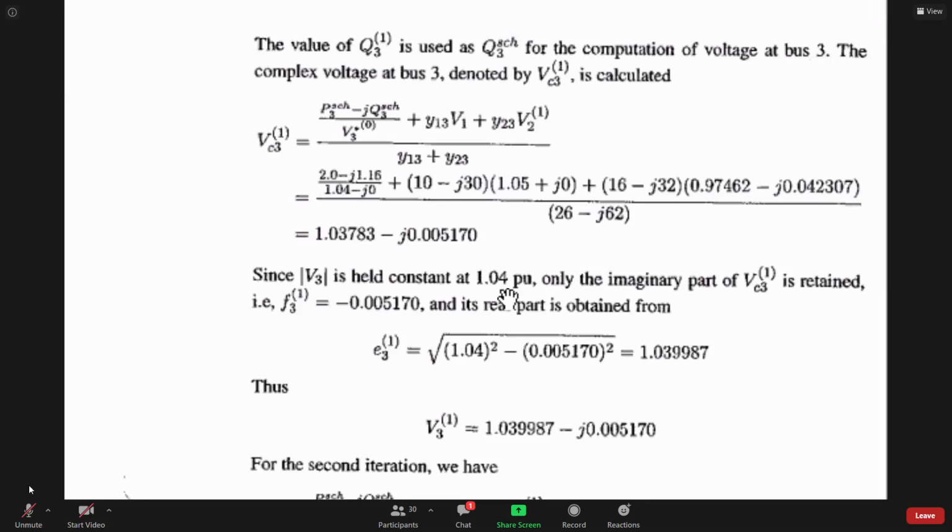That's why the bus is known as a regulated bus, not a generator bus. You have to regulate that voltage at that level, and do the job accordingly to get that voltage. This is the crucial point for these types of problems, so that you can generate your voltage at that magnitude constantly.